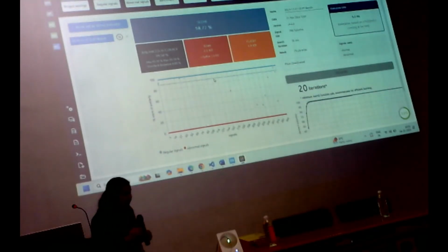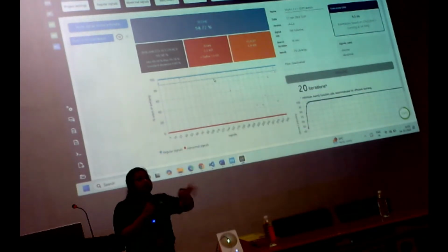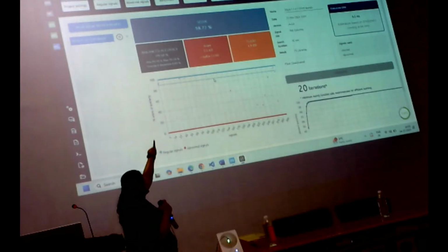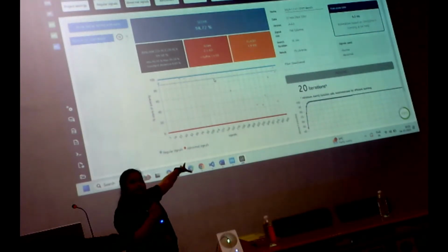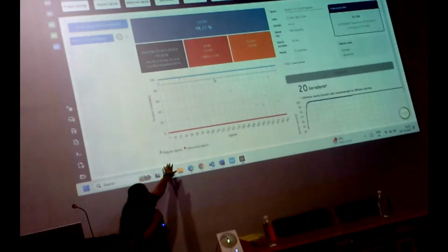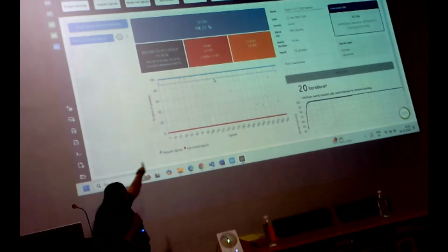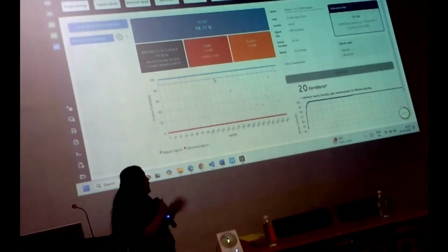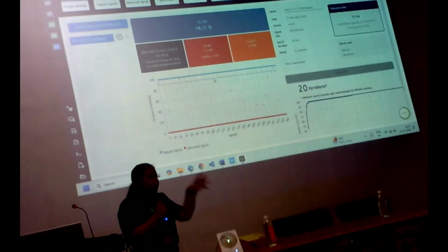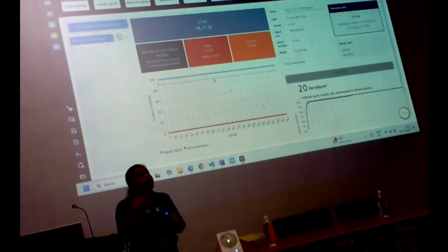The benchmark process is where, after collecting the data, you run the model. Based on your data collection, it will give you the accuracy. Can you see the score? This is the overall accuracy of the model which you have built. And it will distinguish between regular signal and abnormal signal. The 0% is your abnormal and your blue line is your abnormal data. The output which you will be seeing at the next step will be in the form of a similarity score. If it shows 100% similarity score, it is a normal data. If it's giving 0%, it is an abnormal data.